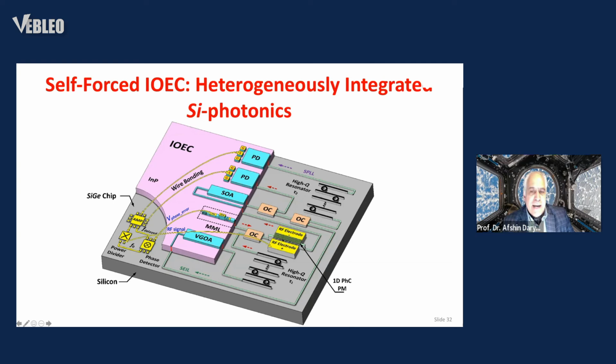And we have the realization of the delay using the add-drop filters, with 2 different time delays of tau2 and tau1 for the self-electrical injection locking and self-phase locking, where the instantaneous RF frequency and RF phase are being compared against the delayed version. And any differences are going to be corrected using the phase lock loop as well as the self-injection process.